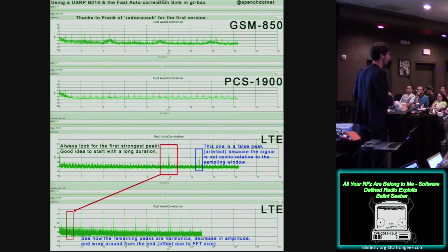And if you were to do the same thing for 3G CDMA, then you will also get a really strong peak at 10 milliseconds. And if you actually look at the standards, that's the rate at which the system sends out this same information, this repeating information about the network. So it's a fixed bit of information that your cell phone will try to find and then look up here. And so if you have some unknown signal, you can put it into something like this,